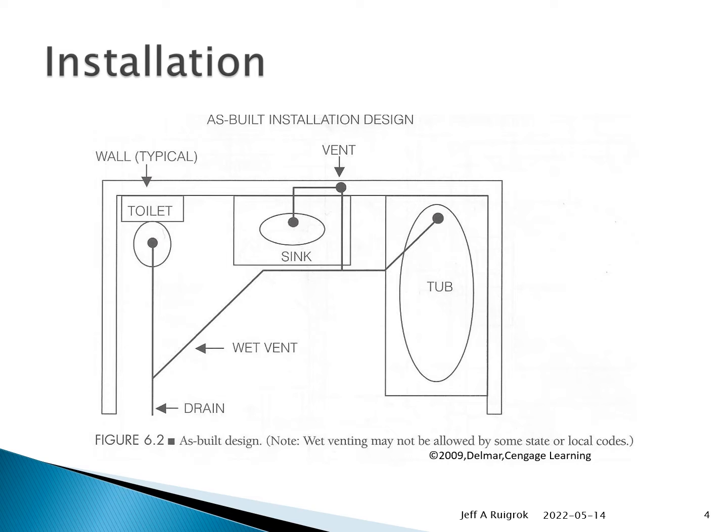I should add that you would generally not have this T here. You would have a 45-degree elbow and a Y. So something like that, and you would eliminate this piece of pipe in here. And that's because you'd never want to lay a T down. You never want a right-angled fitting lying down on its side, as the flow of the liquid hits that T, it would slow down too much. Anyhow, that would be one thing I would correct here. But other than that, this is that same bathroom, but with professionally applied piping, not architecturally applied piping.